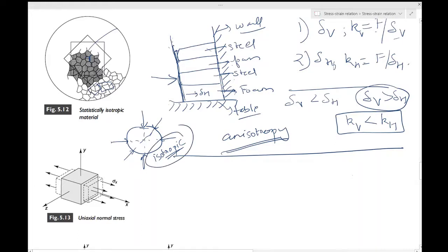Time permitting, towards the end of this course, I will discuss anisotropic materials, which would lead us to composites like bone or wood, which I have given you as examples. The fibers are arranged in a direction, so the stiffness along those fibers will be larger compared to, say, a direction which is perpendicular to those fibers. We will not discuss them right away.